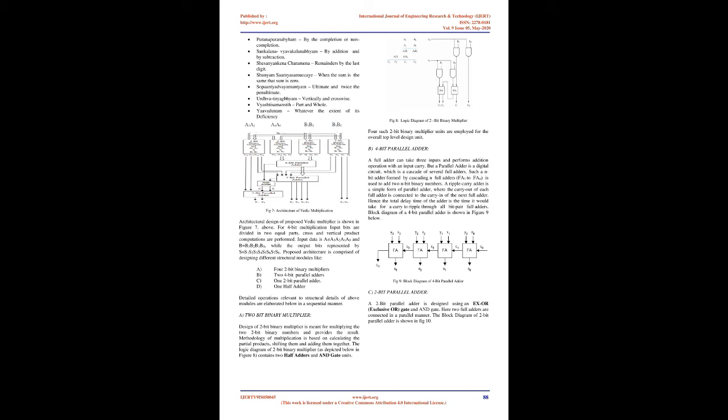Here the multiplication process is divided into sequential steps such that in each step, the generated partial products are added to an accumulated partial sum. Further, the partial sum is shifted to align the accumulated sum with the partial product in the next steps. Therefore, every step in a sequential multiplier includes three different operations: generating partial products, adding partial products to the accumulated partial sum, and shifting the partial sum.